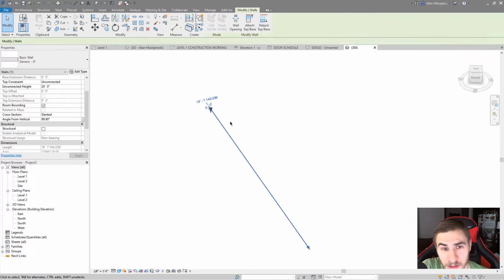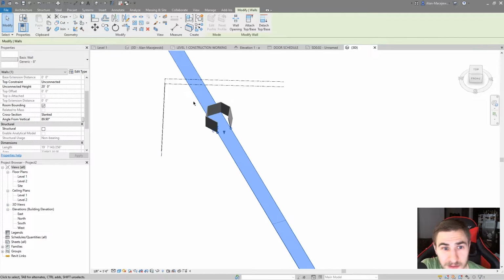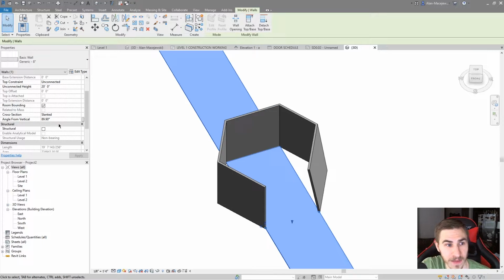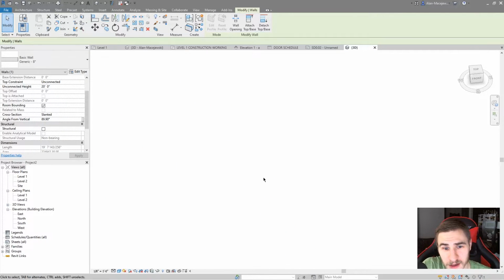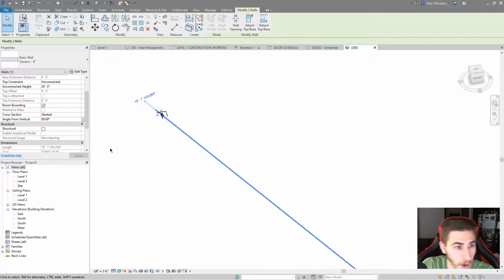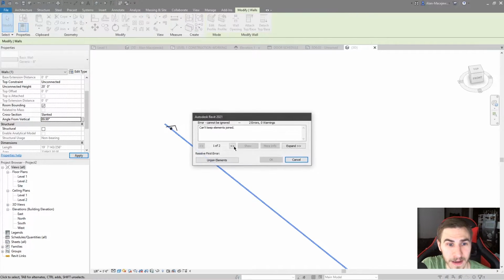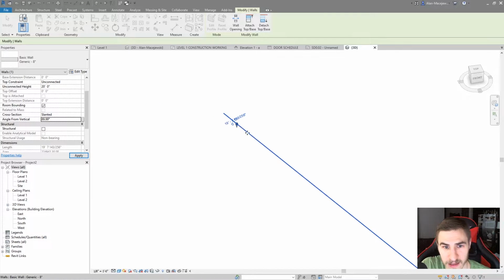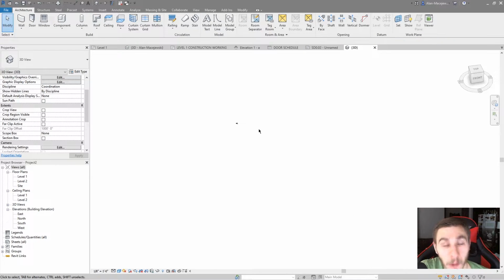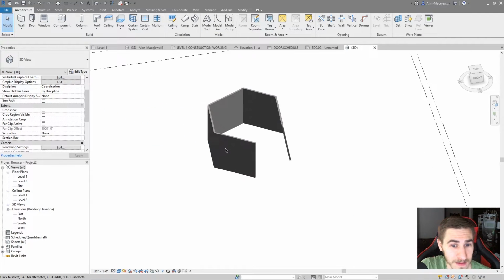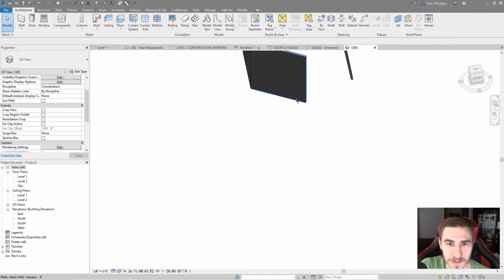This, unfortunately, is the type of thing that I think was half-baked within Revit. I don't know a good way of limiting the values that you could put in here unless you limit it to 80 degrees, 70 degrees, I don't know. But the fact that you can get this kind of result is, in my mind, kind of stupid. But just to be aware, you can go this high if you want. I can imagine I can even go to 89.99, and sure enough I can, and it gets even longer. I have mixed feelings about this, but just be aware that you can do that. People can do that, and it will happen. Just so you know.